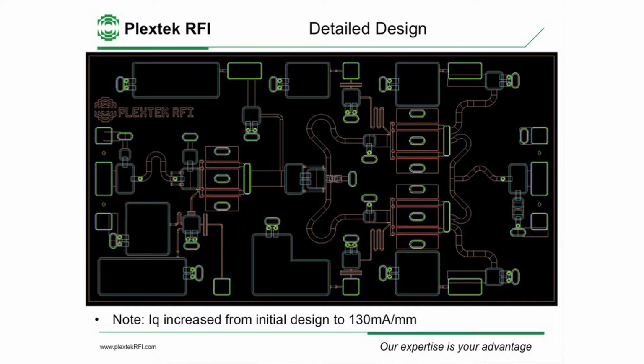You can see we've got 2 output devices, 1 millimeter each. They're combined here at the output. This is some capacitive matching. See, we've got 2 capacitors here. We've got 2 capacitors there because that means we can use a larger capacitor, and smaller capacitors have degraded ESD performance. And the larger capacitor is also more immune to variation with process tolerance.